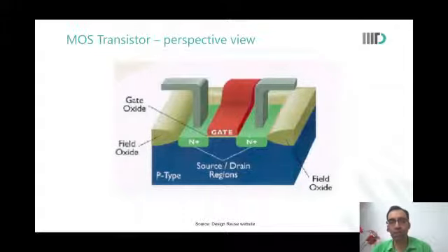From inversion to body, but that is the same medium. How can there be a capacitance between the inversion layer and the body? That is all silicon. If any charge needs to flow, it will flow. There is a depletion in between inversion and body, so there is a small depletion capacitance. But current flow can happen. So between inversion and the silicon body, there is no capacitance. It cannot be, because they are connected. Charge will flow.